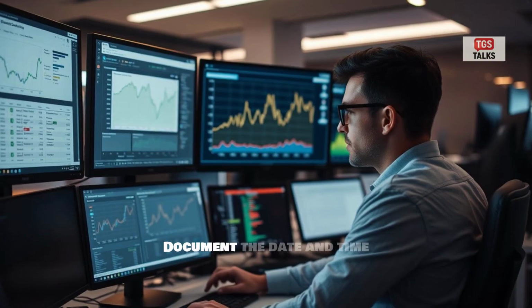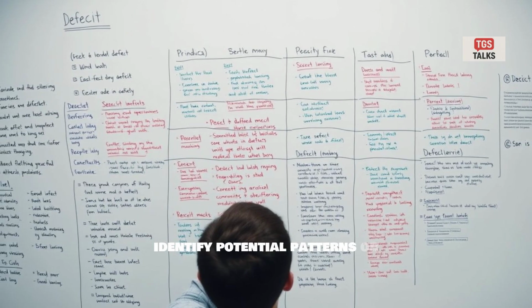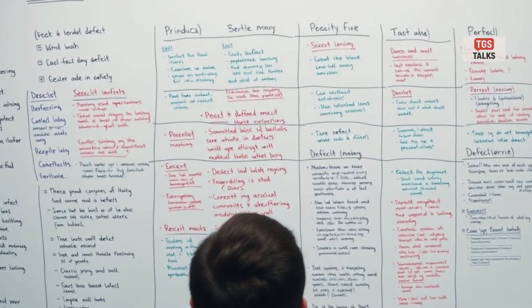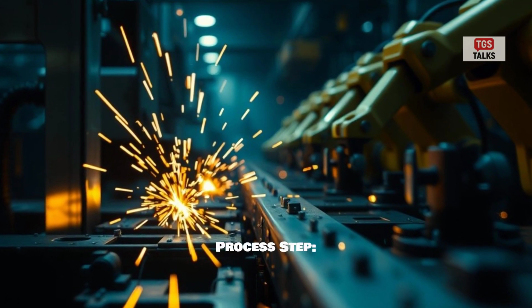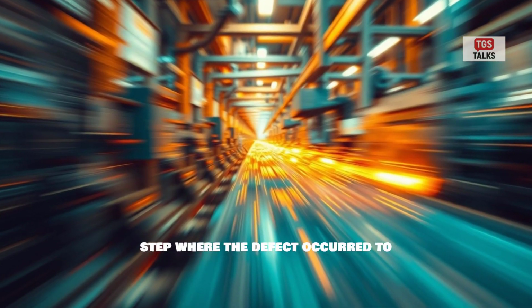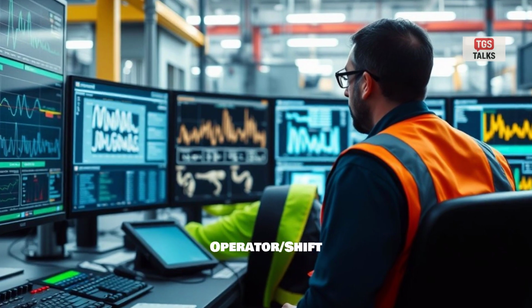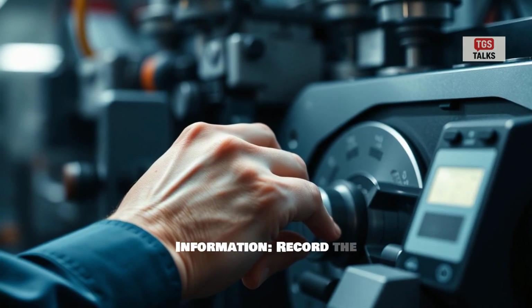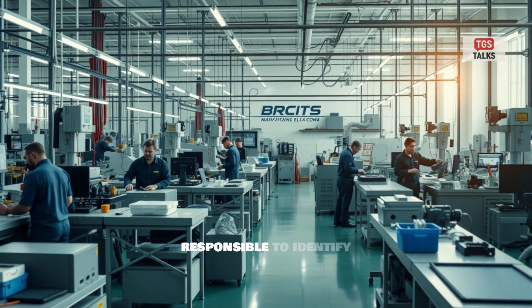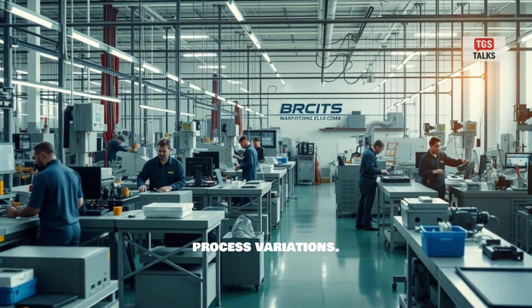Occurrence time: document the date and time of defect occurrence to identify potential patterns or trends. Process step: identify the machine or process step where the defect occurred to focus corrective actions on the relevant area. Operator and shift information: record the operator or shift responsible to identify potential training needs or process variations.